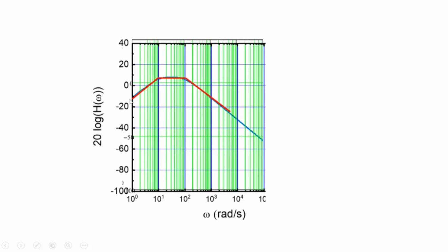But our method captures the sketch of the transfer function quite accurately, and we are able to see what this circuit is doing. We can see that it's attenuating lower frequencies, lower and lower. I've not gone below this, so lower frequencies are getting attenuated. Higher frequencies are also getting attenuated. In between, there's a band of frequencies which is passing reasonably well through my circuit.